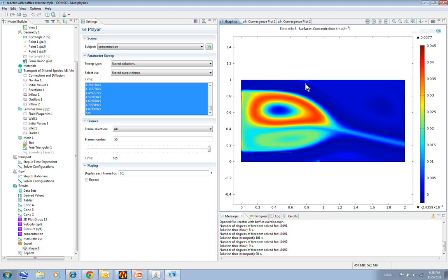and you can see this is where the highest concentrations are. Apparently what's happening is you can see this dark band up here. That's the main flow, and that's actually got the lowest concentration of C in it. So what's apparently happening is that you have a concentration of C here in this eddy between the two flows, and that's a fairly high concentration, and some of it seems to be getting swept out and moved along here. This light blue band could also be from these two streams coming in contact.